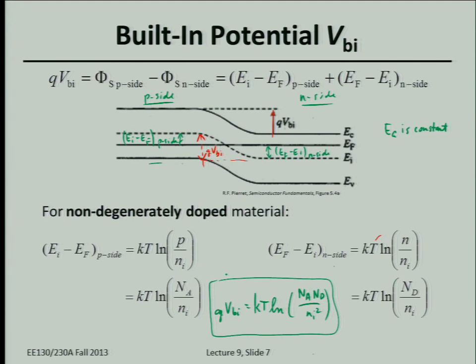So if you have a larger concentration gradient to start out with, you need more drift current to hold it back and balance it out. So you need to have more built-in potential to hold back the diffusion. I think qualitatively, that might be easier to remember than your correct long answer.